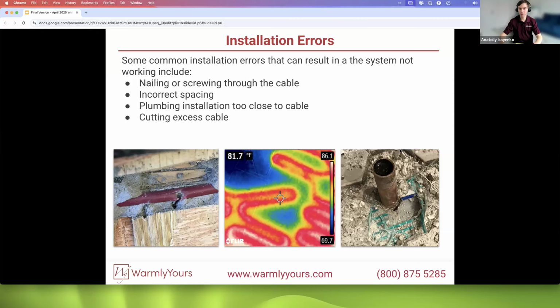Yeah, 100%. Let's start in the order that we have on the screen. The first image all the way to the left shows us a cable, and we can clearly see there's a hole. Pretty much a nail or a screw went through that wire and damaged it. Very likely that was during a nailed-down wood flooring installation. Maybe that spacing or sleeper orientation was not followed. But that's just direct damage to the wire, and we're going to talk later in a slide about how to correct that.